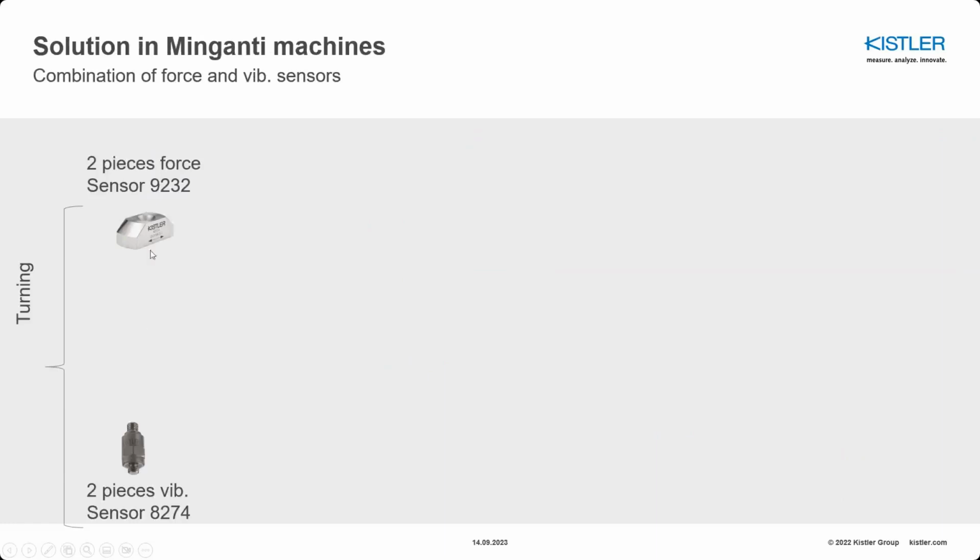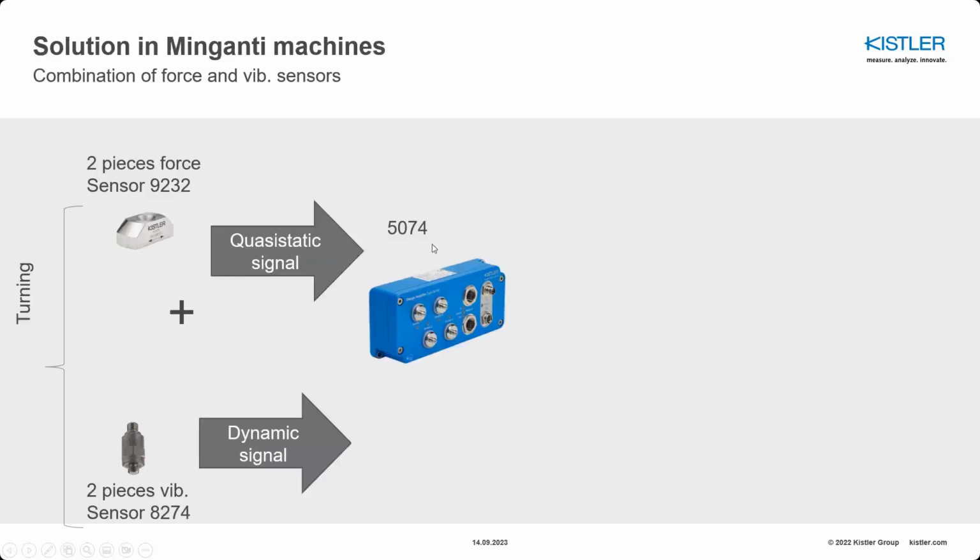So we are utilizing this piezo strain surface sensor that we are putting inside the machine. And in order to have redundancy, we also have a piezo vibration sensor that we are using, and then they are connected directly to our industrial charge amplifier, right? One is a little bit more of a force measurement, as I said, a piezo strain sensor, so it's really measuring the force in an indirect way, since you are measuring the deformation on the surface, and at the same time vibration.